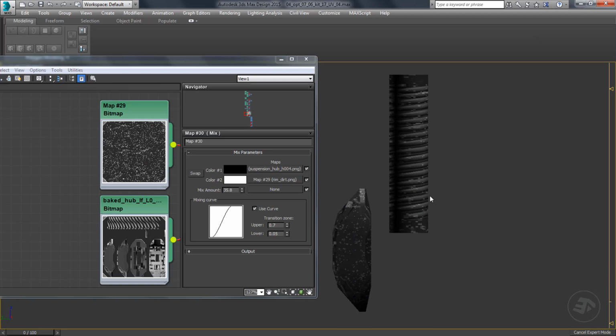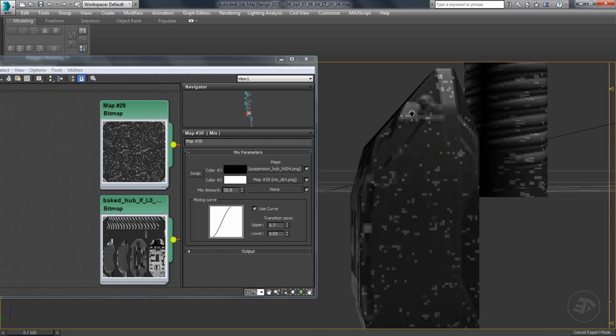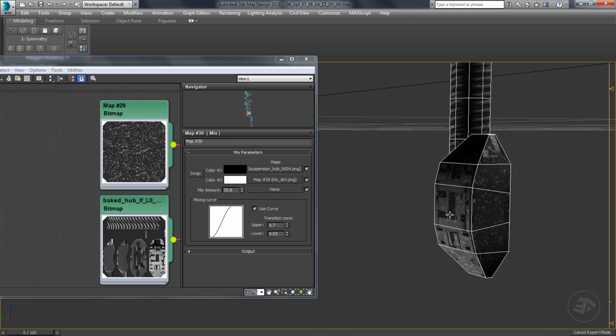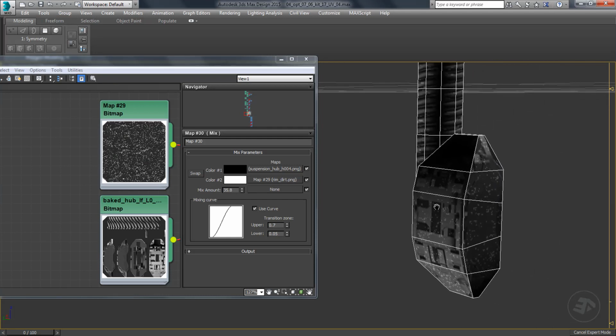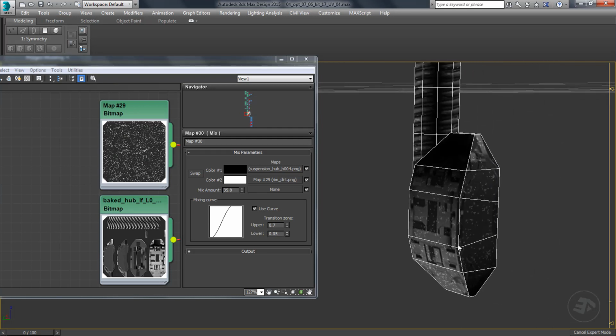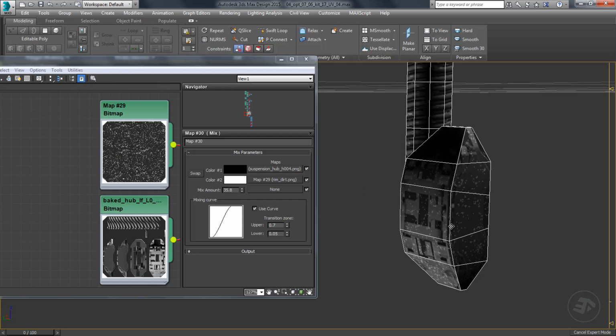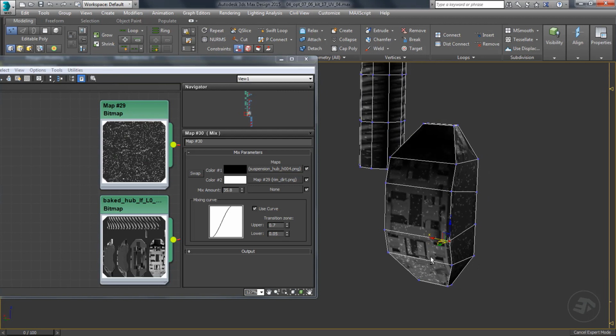Although the dirt map rendered almost perfectly upon this object, sometimes we are limited within the default channel UV. And this is exactly the right time to start utilizing one of the most valuable features of a 3D object when it comes to texturing, which is the multiple UV channels.